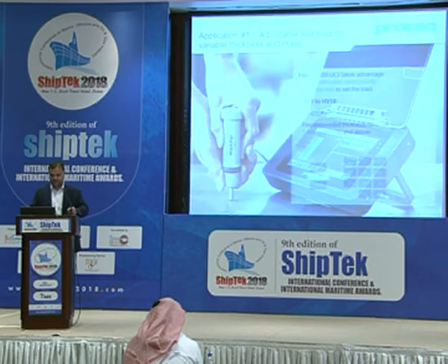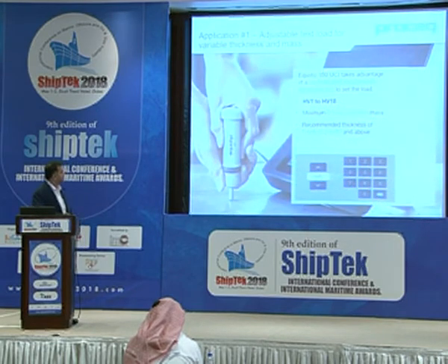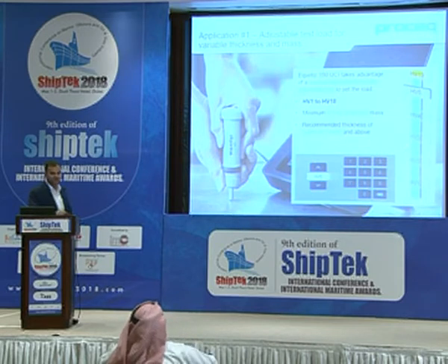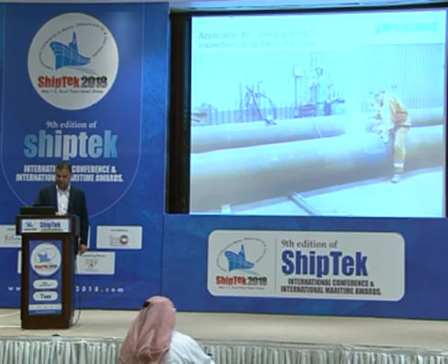Different applications, there are, this is where the adjustable test load for variable thickness and mass, here from HV1 to HV10, it's minimum 0.3 kilogram mass, recommended thickness for 5 millimeter and above, basically. If you just look at here, so this is where all different test loads are available with the inclusion of HV10 recently. So basically, with the drop down on the screen, we can just select the appropriate load and then we can do the test.